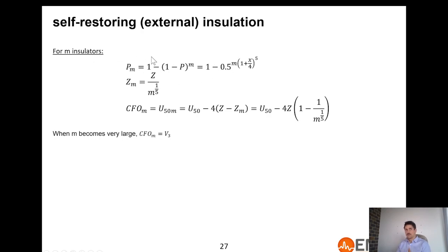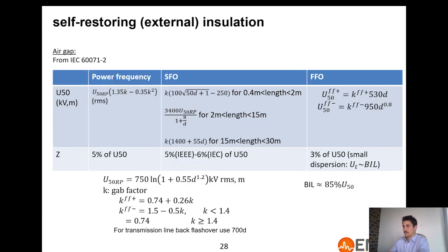And if you have surge arresters, you can just cut the line in smaller sections and assume the voltage will be the same for the section, which is a safe assumption.